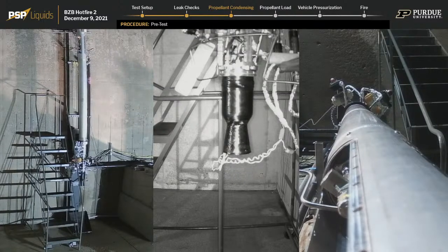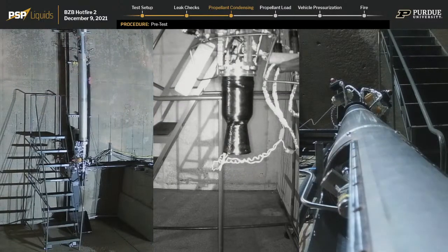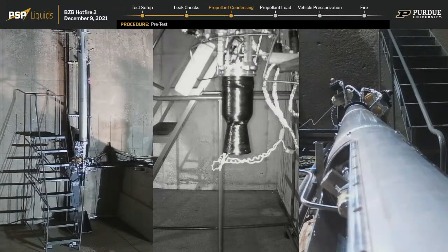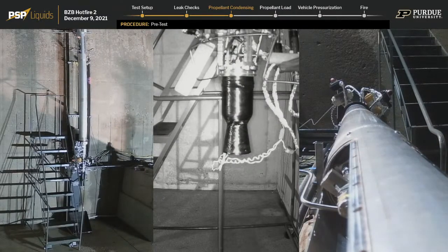Although I see there is some suggestion in chat to use Creo, one of the major benefits we get is PDM. So do you want to talk about what PDM is and how we can teach new members it in an industry-relevant manner? Yeah, so PDM stands for Product Data Management, and it's a software that we integrate with SolidWorks to let all of our members have revision-controlled access to our part drawings, documents, and assemblies. So what we can do with this is prevent people sharing around documents individually and having out-of-date part drawings and CAD files floating around.